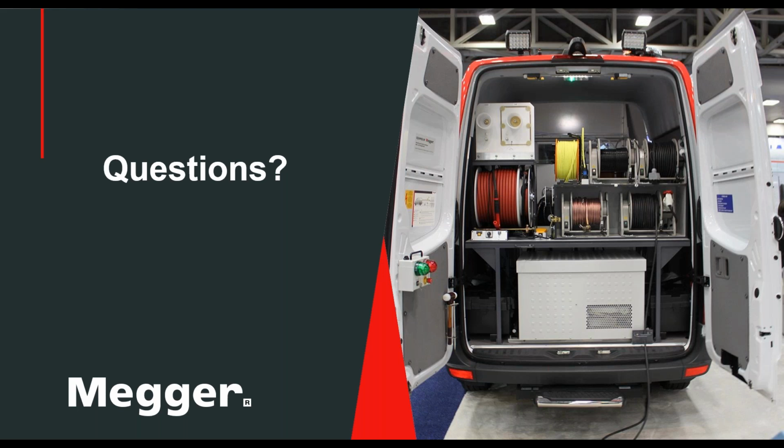I may not understand this question correctly, but what we're going to do is a breakdown test that tells us how much voltage we need to use. And of course, we can control the voltage output of our thumper. So the joules is going to be a result of the thumper we've chosen, because it has a set of capacitors in it, and the voltage level.